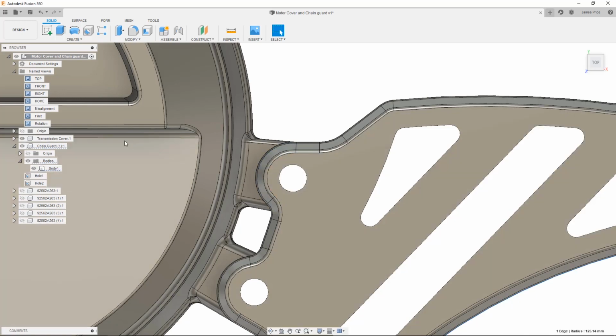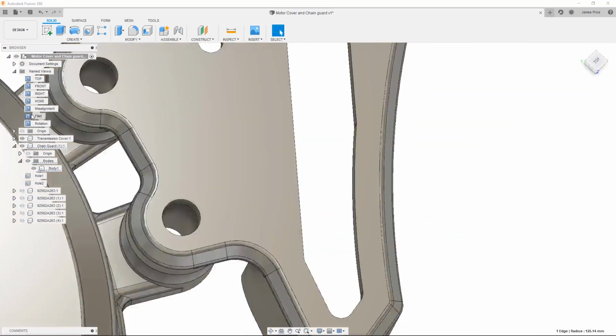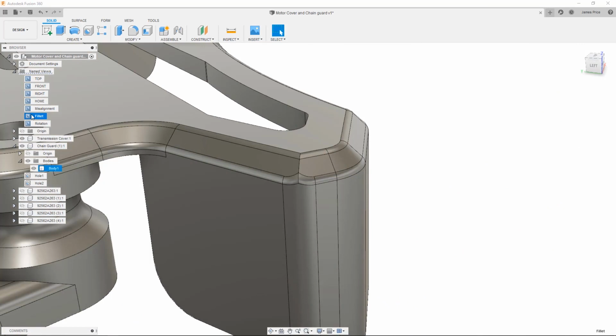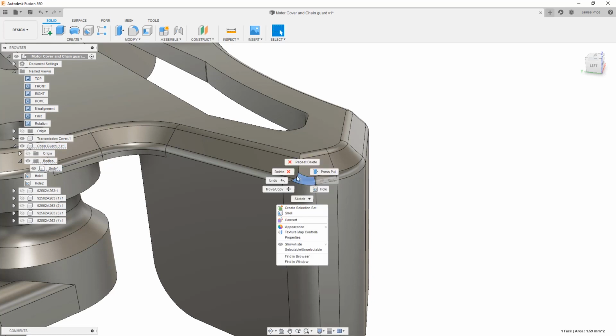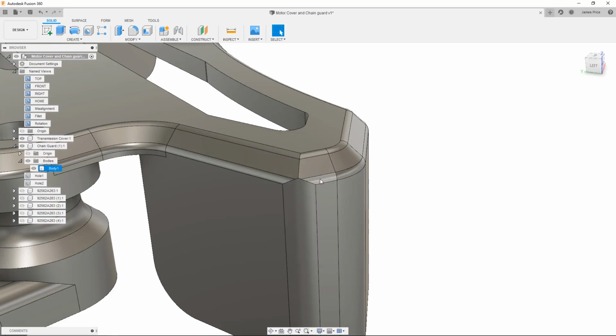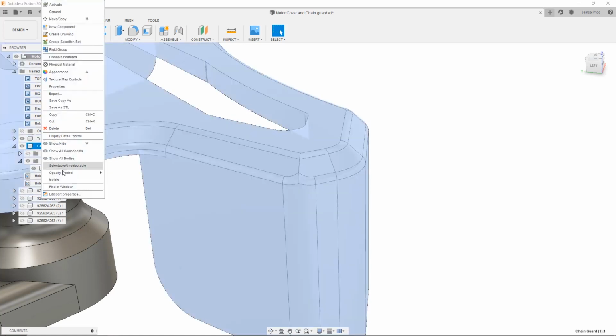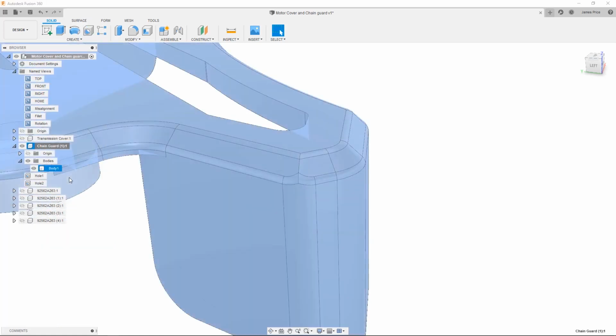The next issue is the fillet. Here you may consider manually selecting each fillet and deleting, although this can be time consuming. Also, with direct editing, Fusion calculates the shortest or most efficient healing based on surrounding edges or faces. At times, this can be problematic if an optimal solution cannot be found, as shown here. In this case, it would be better suited to remove all connected fillets in one action, then reapply.